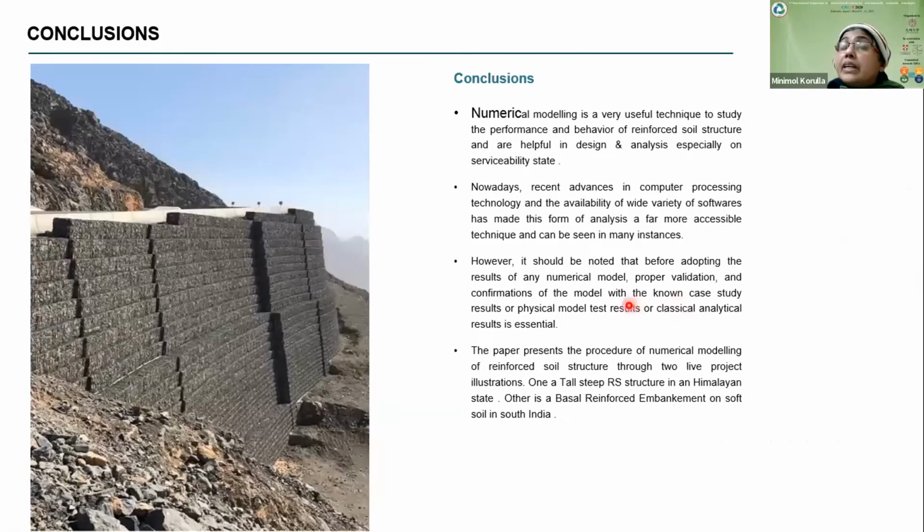So the conclusion is that numerical modeling is a very useful technique to study the performance and behavior of reinforced soil structures, whether it is a reinforced soil slope or a wall or a basal reinforced embankment, with recent advances in computer processing technology and the availability of a wide variety of software. It should be noted that before adopting the results of any numerical model, proper validation and confirmation of the model with case study results, physical model tests or classical analysis results is essential.